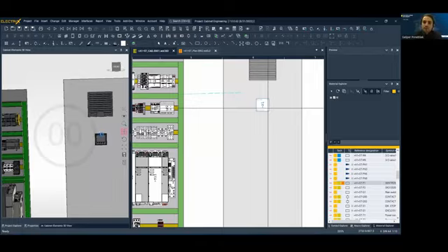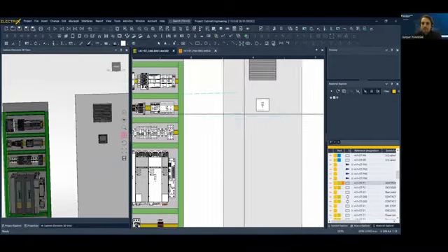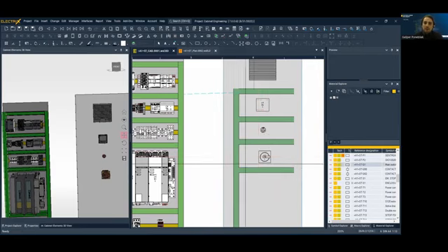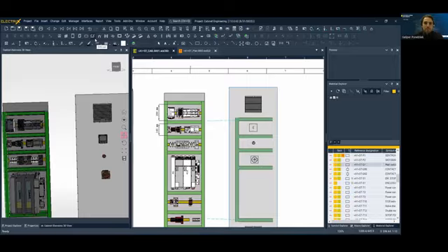So before you saw some cable ducts here. These are virtual cable ducts. Actually, they are placed on the opposite side of the door. And we can place these virtual cable ducts, but what we have to be careful about is that we also insert this virtual path. This virtual path, you can see it's a blue dotted line, and it's because of routing. We have to place it so that when we do the routing right now. So now we have all elements.